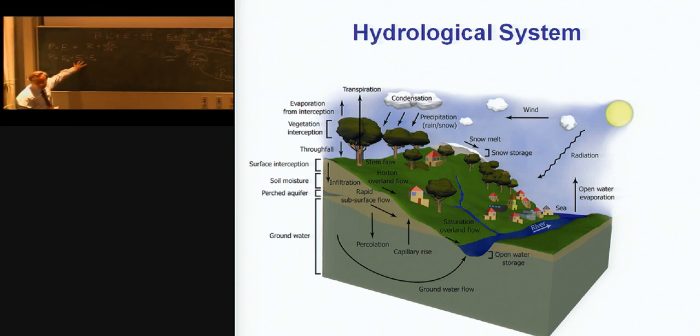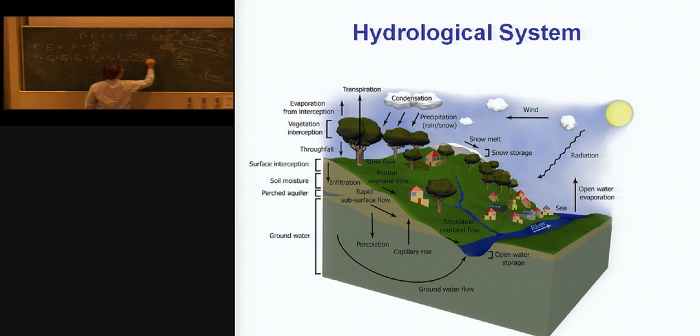Yeah, these are the three main evaporation fluxes. Plus runoff, we have runoff at the surface, RS, runoff in the unsaturated zone, RU, plus runoff in the groundwater, RGW. Yeah. Plus we have a number of dS/dt, make an I here. These are a number of storage changes per time step.